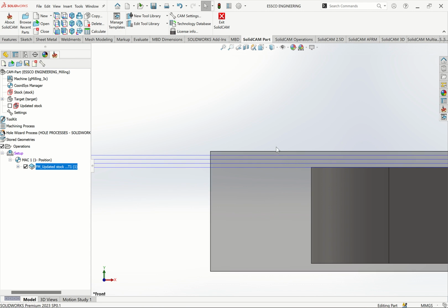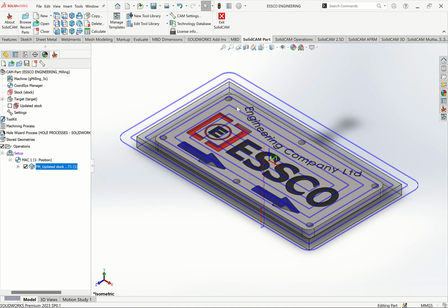So it is 2 divided by 0.5, you get how many passes? First pass, second, third, fourth, fifth. So that is what you're able to do. If I do 2 of them, 1 millimeter, it goes 2 times. If I do 1.5, it may go maybe 1 time plus, that's 2 times. Then you calculate the remaining. So it depends on the depth amount you have put.